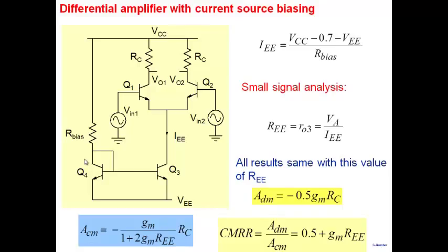Directly connect a voltage here? Well, how do you generate a voltage? If you look at it, this current that you flow here eventually generates a voltage at this particular node, and this voltage is what biases Q3. So you can think of it as a bias circuitry for Q3. You're right, all you need is a voltage at the base.